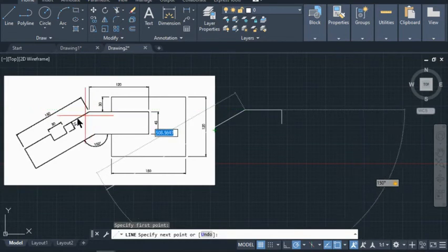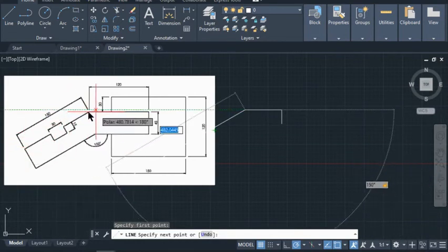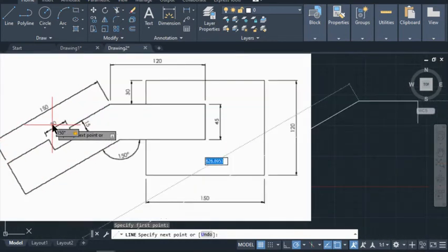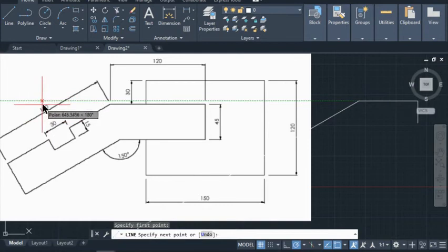So first of all, this whole length here is 150. In the middle, I have 30 right there. All right, so 150, subtract that 30, I have 120 left. 120 divided by half, because I have a section up here and a section down here. So 120 divided by 2, I have 60 for each of these. So I'm going to draw 60, and then I draw 30, and then I'll draw another 60.